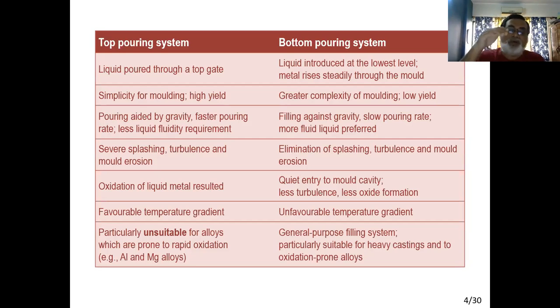And as the liquid is colder, its specific gravity or density will be a little bit higher. The liquid metal you pour last, because of the high temperature, has a slightly lower density. As a result, the last liquid will always stay on top, and the first liquid will always stay at the bottom.